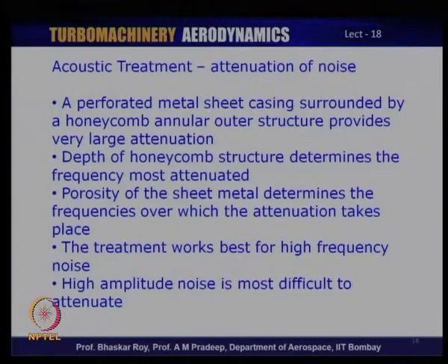Now, this treatment of using perforated metal sheet and honeycomb works best for high frequency noise, which I mentioned earlier actually carries low power. The high amplitude noise which carries high power is actually more difficult to attenuate, and now we know why, because it actually carries high power.